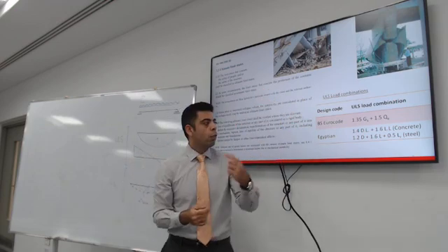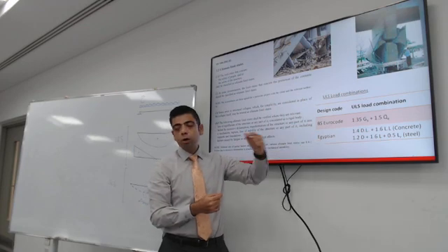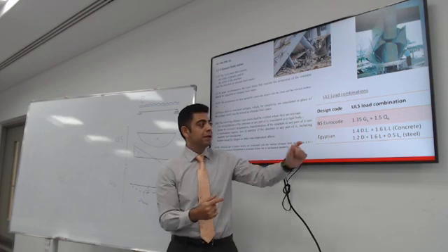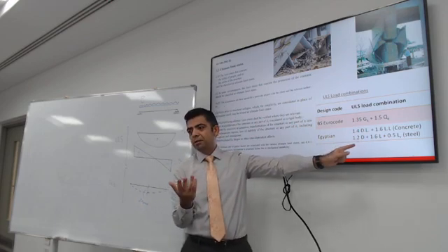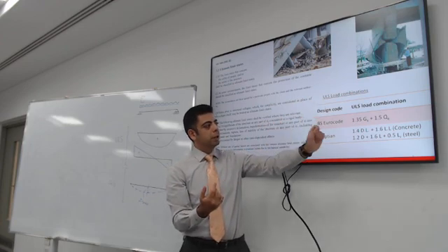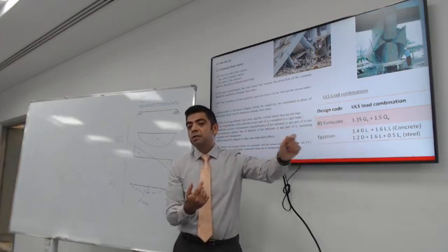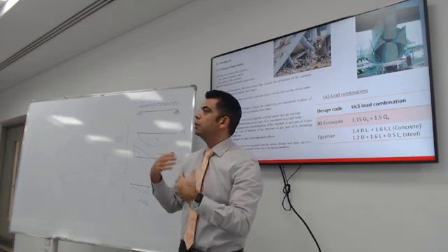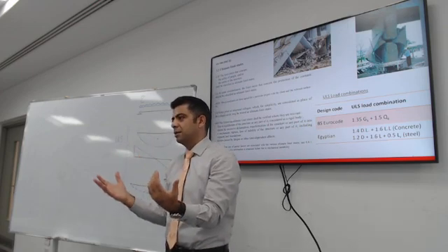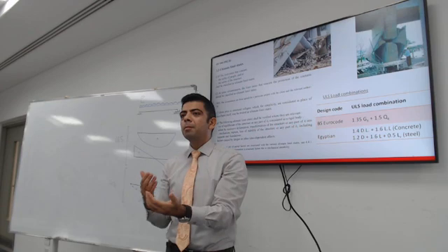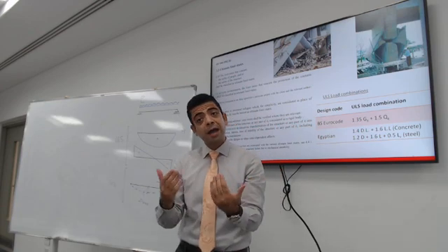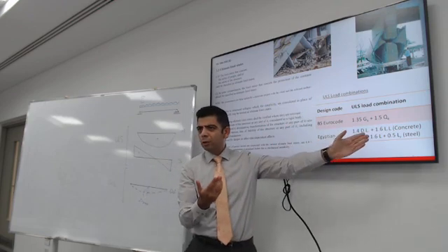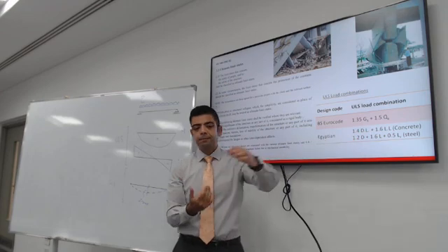I need you to understand what the Eurocode and the Egyptian code call these five loads. The Egyptian code will call the dead load D. The European code will call the dead load GK. So now it's a matter of picking a book and starting work. You understand what you need to do. You need to get dead load, live load, and the combinations. Now, where is your project being built? Built in North America. Fine. Where? Canada, United States. All right, let's get the Canadian code and look up what they call the dead load, what they call the live load, and use their load combination.